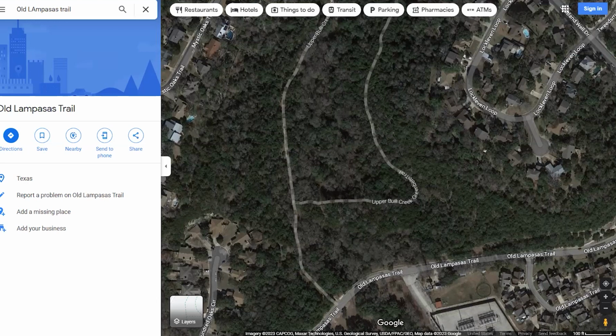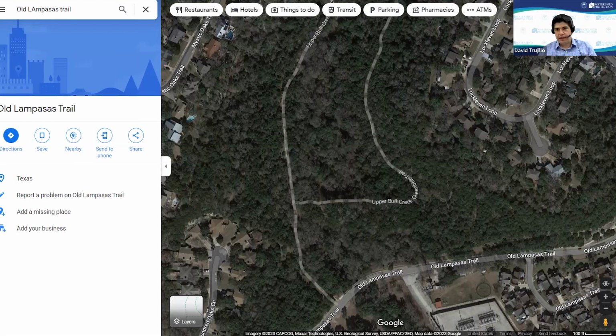I asked the question about the tree. What does the marking mean? They were surveyed, but does that mean they were surveyed for removal, or what was the purpose of them being marked? At that point, it doesn't really indicate. The ones that you're seeing don't indicate whether they're staying or being removed. We just needed to survey the trees that exist on site, and then we're only removing the ones that are in the way, in places where we're regrading the dam, or trees that are not supposed to be there per dam safety regulations. But the markings themselves are just part of the survey.